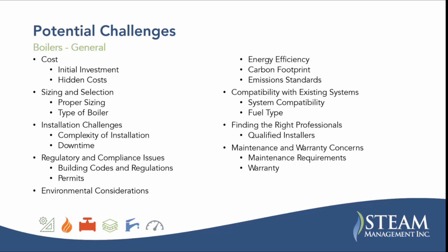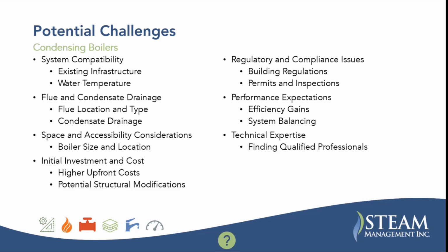We'll talk about condensing boilers in a second, but this is just kind of general. And then you have maintenance and warranty concerns, so making sure that you're covered there with the right selection of a manufacturer. With condensing boilers, there are more issues with system compatibility, from existing infrastructure, water temperature. We talked about flue duct compatibility not being there. You have to account for the condensate drainage.